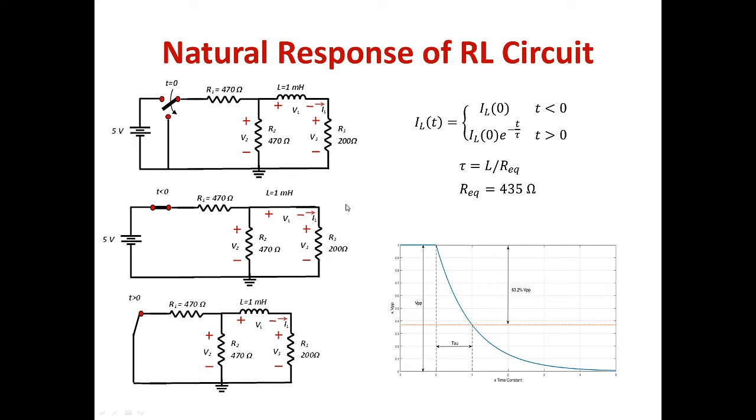In this particular circuit, tau is calculated to be 4.25 microseconds. So let's simulate the circuit in Orcad. Now the thing about simulating the switch with Orcad is that we're going to use a rectangular pulse.